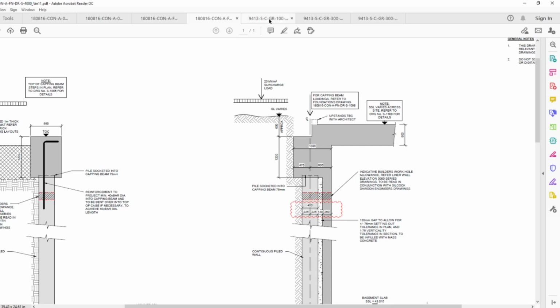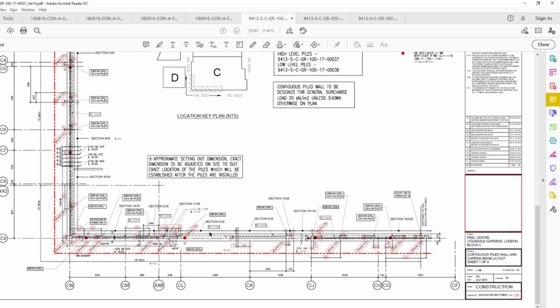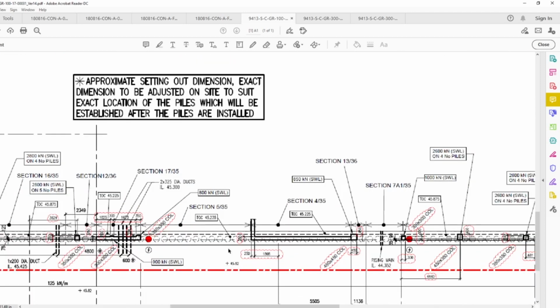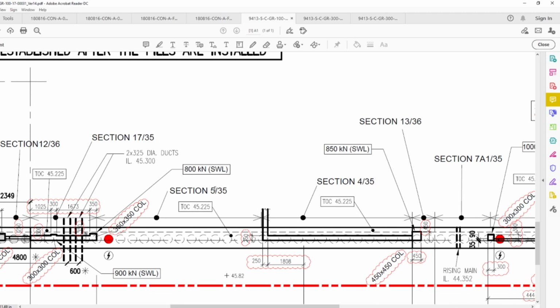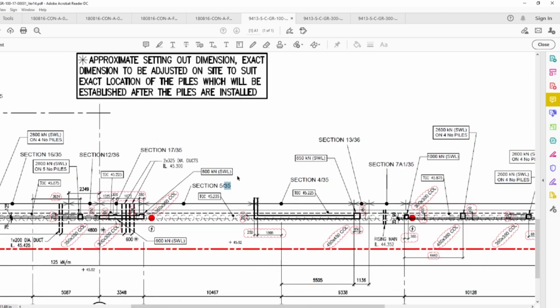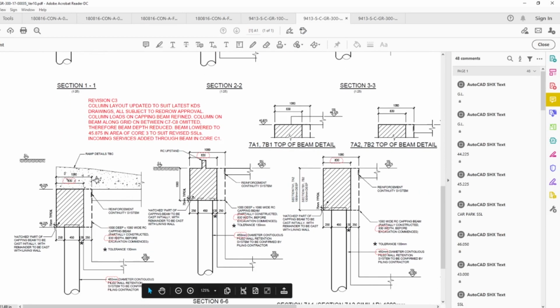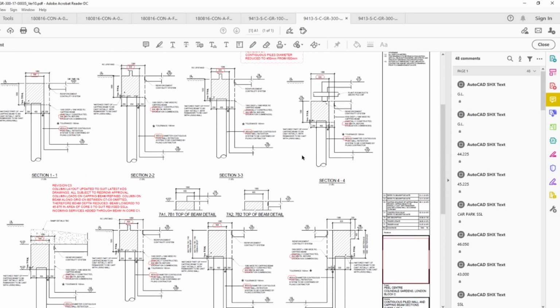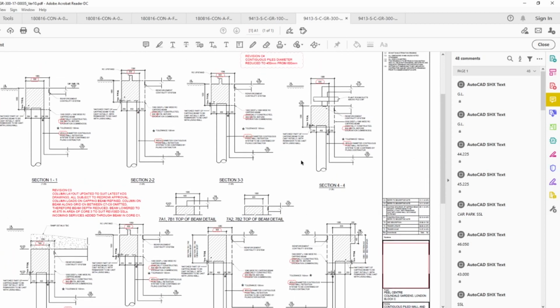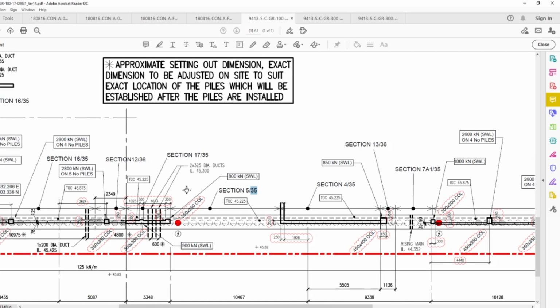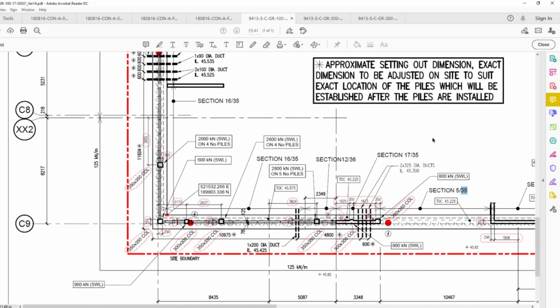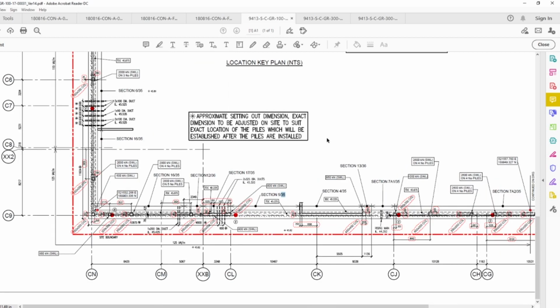So now I'm going to go to block C. You remember this GA here, which was showing the sections. So we know here from this point to this point there is a section 5 on drawing 35, and I'm going to open this drawing in a second. Section 5, so you can see that drawing refers to the sections. It's a big nice drawing here with a loads of sections, so there's a loads of information, but what I can tell you now, the information is provided in a very clear and very good way, because once you got your GA, you know where to refer. And when we're going to be preparing our working drawing, I'll probably move these sections here, and I'm going to do the markups with the different colors, so you're going to see how can you make your life easy.